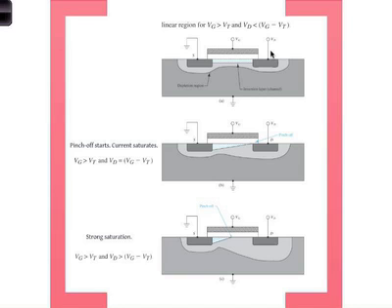If I'm understanding correctly, then basically you can just have, in silicon, have the electrons come up there, and it would act like an n-type. Except that, remember, you need a reverse bias junction over here. Okay? You cannot just have a silicon and just a gate voltage. You need ohmic contacts here. You need to have a reverse bias, otherwise the current will flow without any gate voltage. So you need to have a PN junction there.